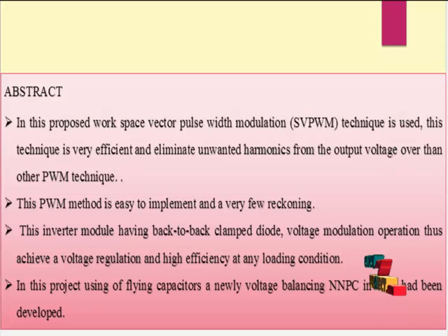Due to the presence of these elements, the inverter can operate normally and the voltage stress is shared uniformly across all switching devices. The capacitor voltage should be controlled, which results in an abundance of switching states. The validity and expected results of the proposed topology are verified by simulation. The inverter design helps to reduce the harmonics, and the result was analyzed in a MATLAB simulation model.